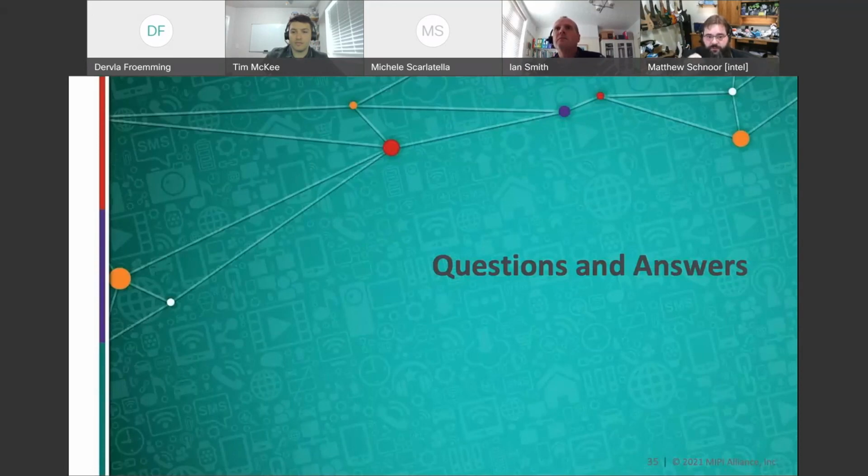You can reset just the peripheral, which is the basic part of the target that handles the buffers. You can reset the whole chip, which is that part plus everything beyond it. And if you have additional parts, you can do specific targeted resets to those different domains within a chip, depending on how complex your chip is and how you make use of RSTACT.